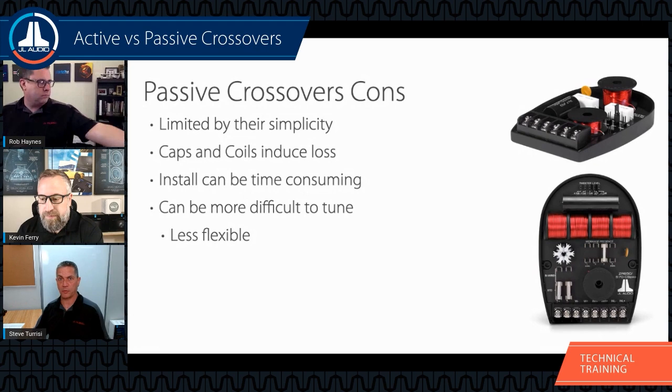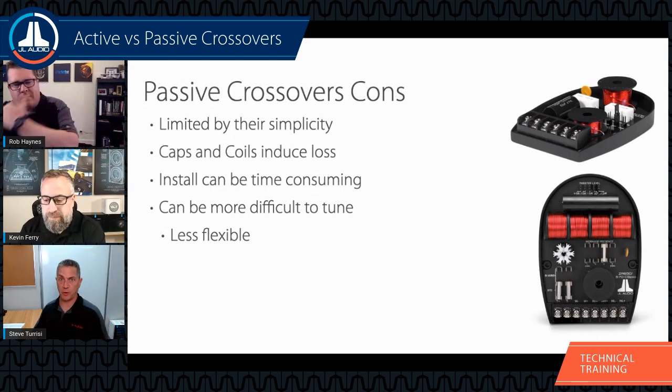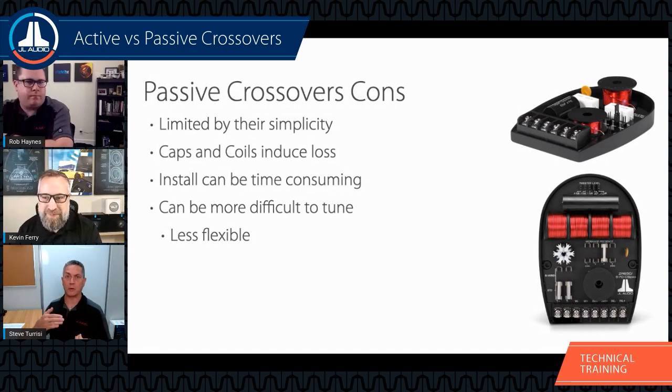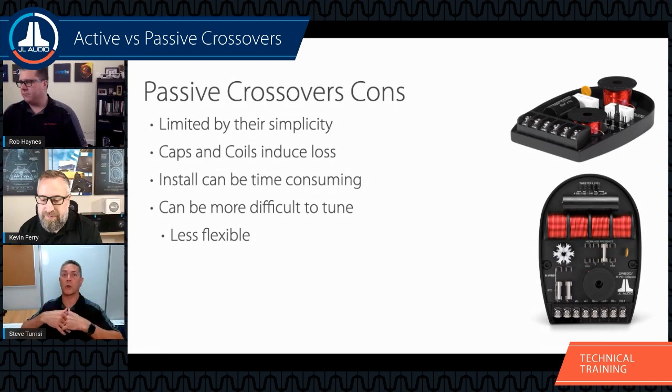Now, what's funny about this is for many, many years, it was always a struggle for us as JL Audio trainers when people would say, well, what's the filter frequency on the XYZ crossover? And it's like, honestly, I don't know. And it sounded funny because, well, how do you not know? Don't you pay attention? It's like, because we started with one value. And then as we listened to it and saw the true interactions, we started changing those values to give the performance that we were looking for. It doesn't matter about the filter frequency at that point. It matters about the network working well together.